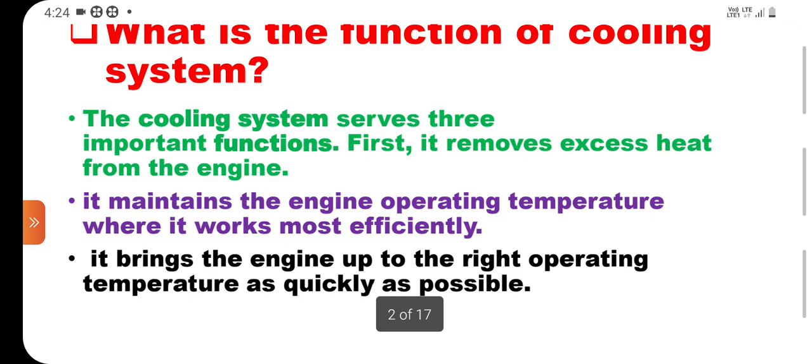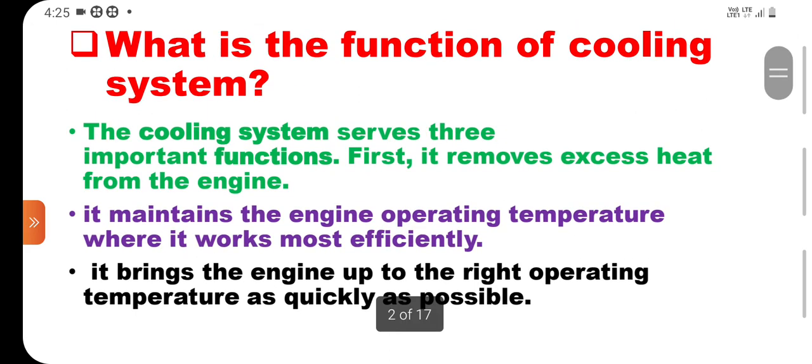That's why, to maintain the engine temperature, there is a requirement of cooling systems. Due to overheating, a large temperature difference may lead to distortion of engine components due to thermal stress.